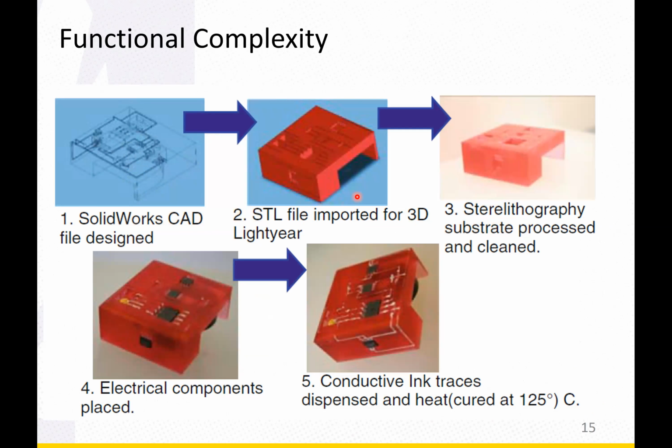The substrate is additive manufactured using a stereolithography-based method, and then the electronic components are placed, and the conductive ink is printed onto this substrate by direct printing.